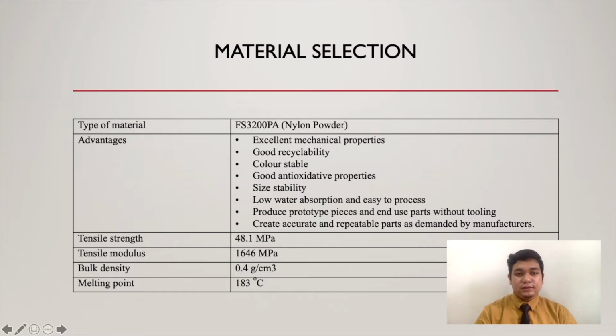The tensile strength of the material is 48.1 megapascal, the tensile modulus is 1646 megapascal, and it has a melting point of 183 degrees Celsius.